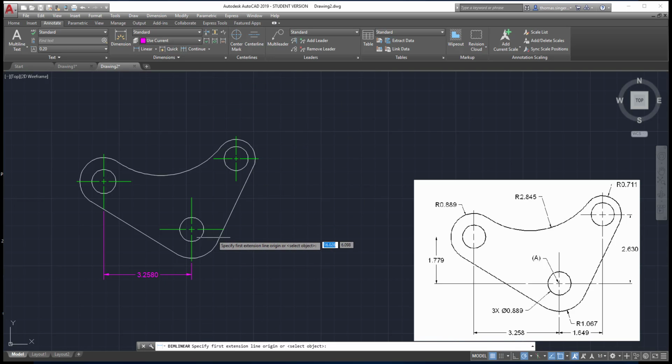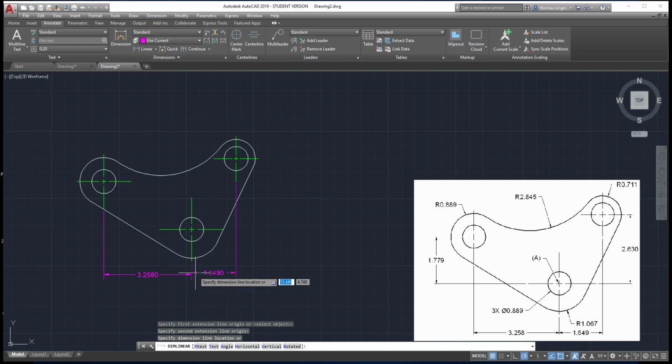And you might be saying, wow, but there's 4 decimal places in the dimension and we only set 3 in the units. Well, if you remember, numbers 5 and 6 deal with dimension style and text style. And then the last one's layouts. So dimension style and text style: the dimension style controls how many decimal places there are.